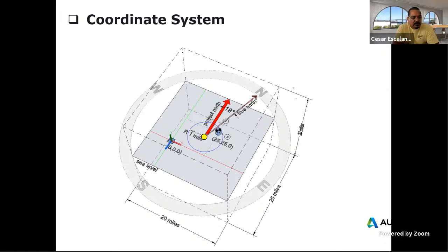And the calculations around visualization and view refresh will not complete inside Revit. And then you may start experiencing strange behaviors, for example, elevations that don't appear, or sections that have crop regions or crop areas that are not rendering correctly, or you send something to print and it's coming out cropped without explanation. So those are symptoms that there is a CAD file or elements in the Revit file that are outside of the maximum 20-mile space.